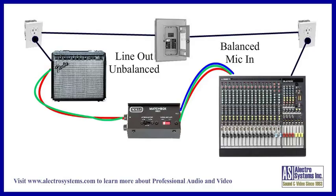In order to do this, we need to break the ground connection between the amplifier and the mixer. Remember that with an unbalanced system, the grounded shield conductor is needed as part of the signal, but in the balanced system, it is not.